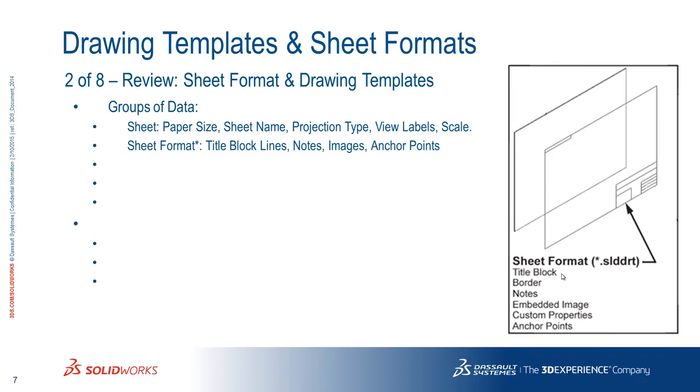Now, the sheet format is something different. That is your title block lines, the notes, the images, anchor points, any custom properties, that sort of stuff. It's a separate item. It has a separate file. And the reason for that will come up a little bit later.